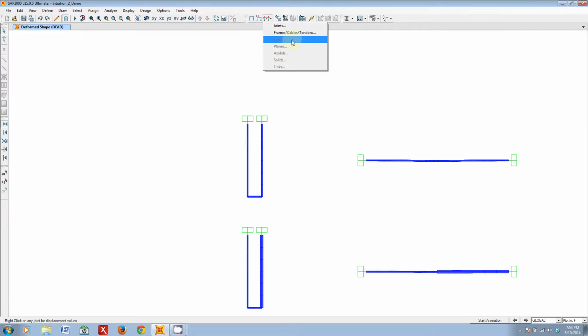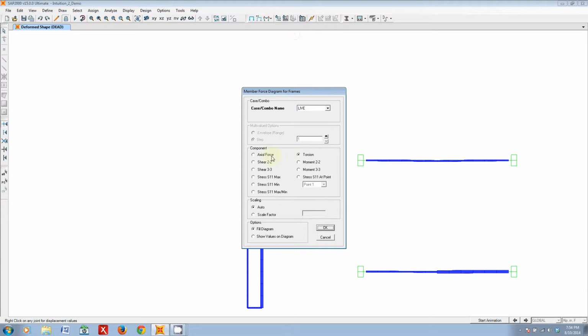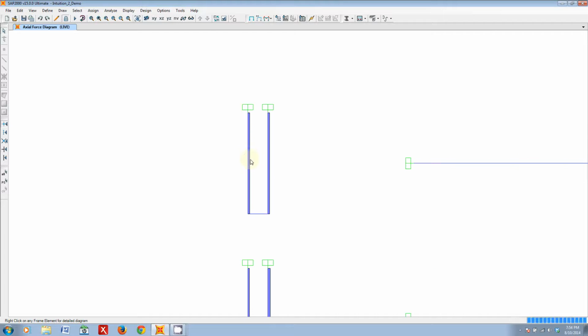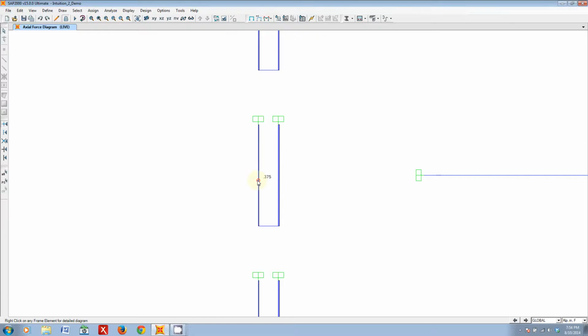Alright, now let's visualize our axial force. In the first case, we can see we pretty much split the load between the two rods 50-50. Makes sense. In the second case, though, check it out. Only about 0.375 of the unit load, that one kip, is getting split into the left member, but a lot of it, almost over double of what the left one is carrying, gets split into the right member. So that load really likes this stiff member much more than this skinny one.